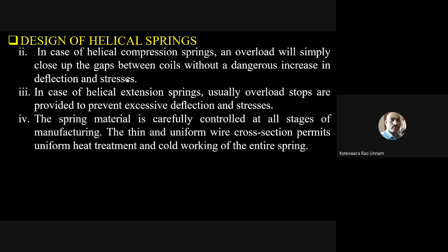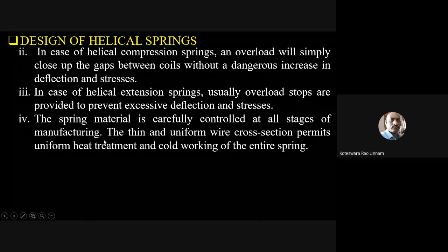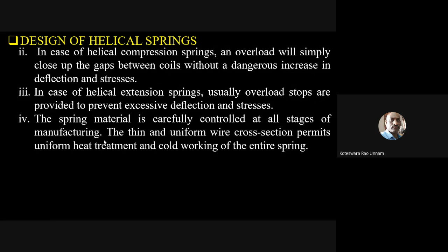Only the factor of safety is taken as low, which is close to 1.5 or even less than 1.5. Then the spring material is carefully controlled at all stages of manufacturing. The thin and uniform wire cross section permits uniform heat treatment and cold working of the entire spring. So, if you talk about the material homogeneity, like already at the beginning I said it.